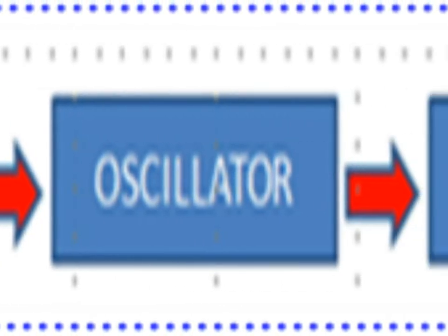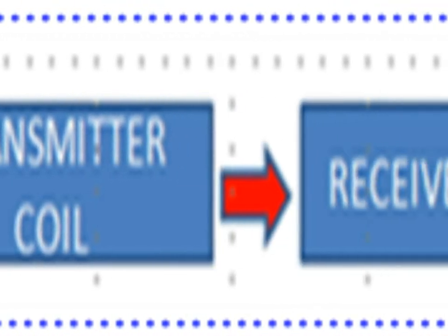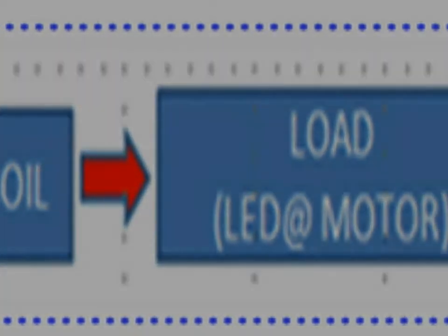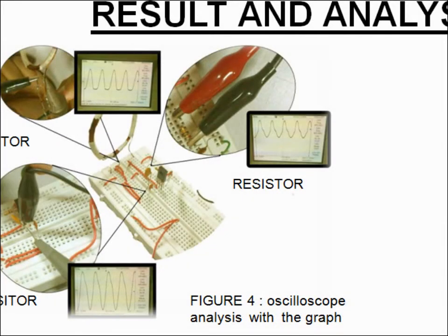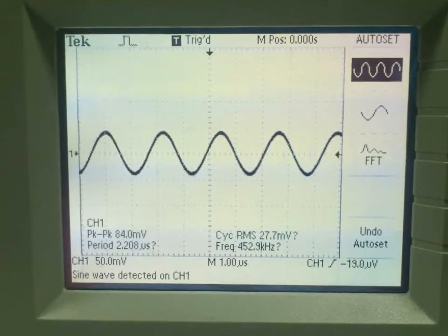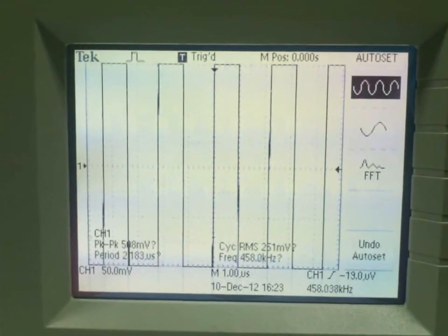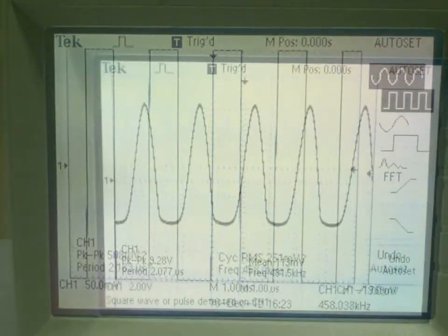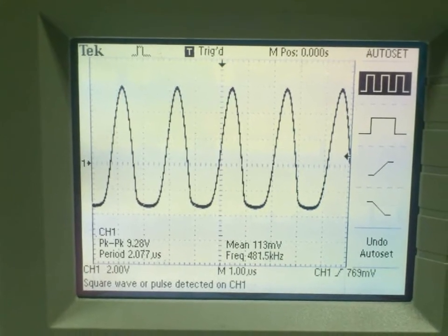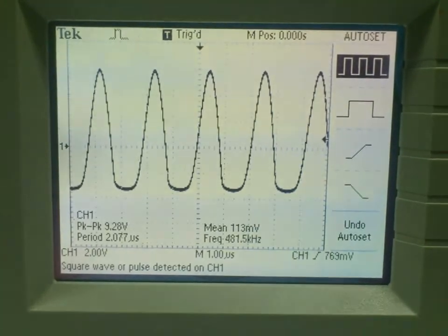A function generator is a device which provides a specifiable voltage applied over a specifiable time, such as a sine graph, while an oscilloscope is an apparatus, a signal analyzer, usually in the form of a voltage versus time graph. By using this, we can obtain the frequency, amplitude, and overall shape.